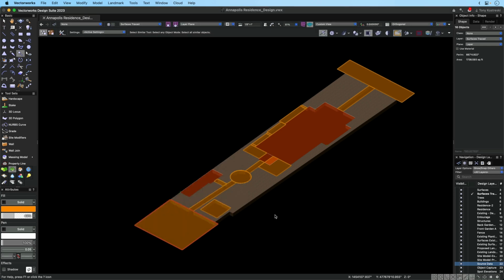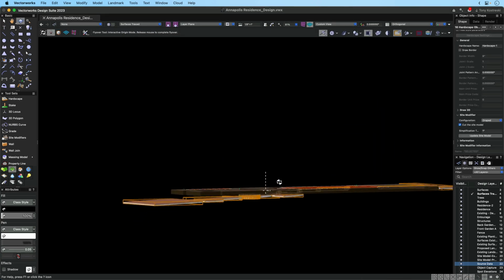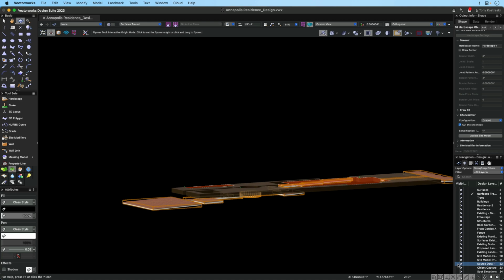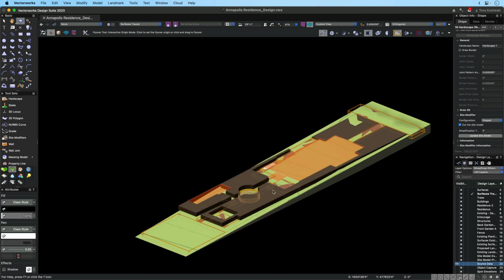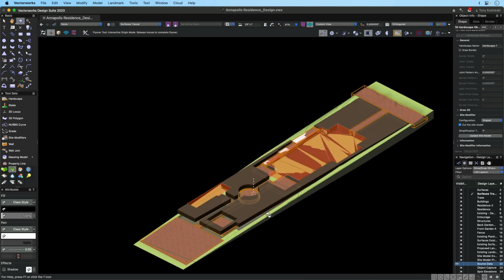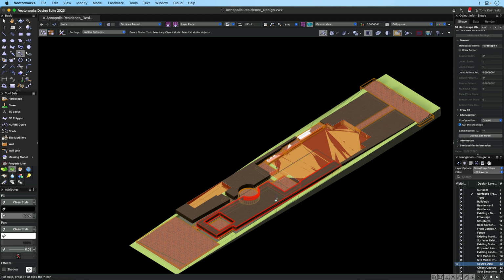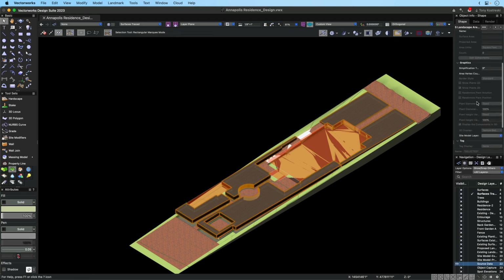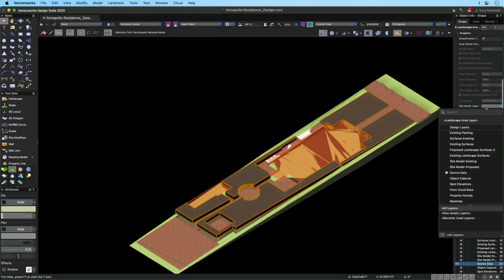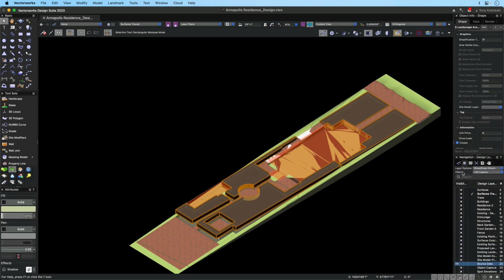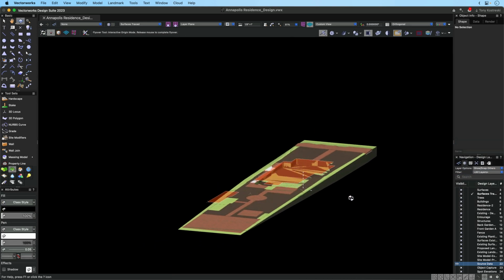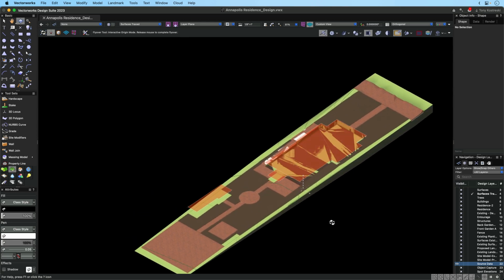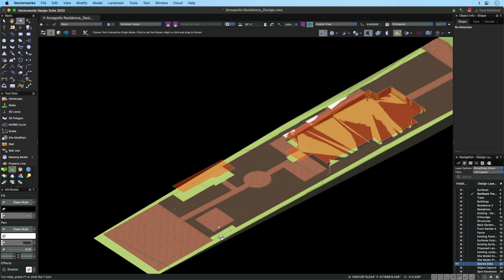So let's go ahead and select that. This will cause all of the hardscapes to actually map to the site model that we have here. Let me just click update so that we can see that that cuts it. And then we can actually tell all of the landscape areas to follow the terrain as well, simply by going into the object info palette and telling it to listen to the design layer that the site model lives on. And like that, we very quickly generated a site model with some of the existing materials that are on site.